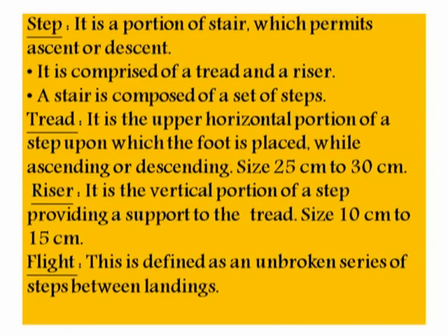It is comprised of a tread. The horizontal part of a step is known as a tread and the vertical part is known as a riser. A stair is composed of a set of steps. So when the steps are constructed in a series, it is known as a stair. Tread. It is the upper horizontal portion of a step upon which the foot is placed.